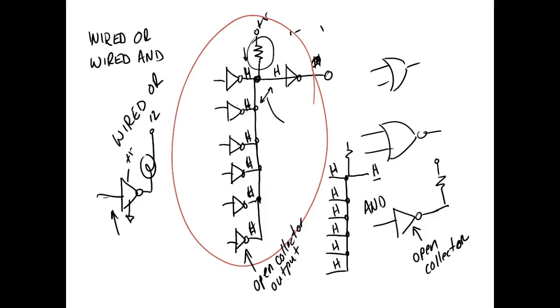Eventually, you can load it and you can short out the output of a standard TTL gate. But you don't need to do it very long, right? You understand? Because it's going to try to be sourcing 600. This other guy was 100 milliamps through that little 130 ohm resistor, and if you do it very long, you're going to mess it up. But it's good enough to troubleshoot. So yeah, we can jump out. We can ground the output of a logic gate without hurting it, so we can see what effect it has down the line. In fact, we got a thing called a logic probe that basically that's what it does. A pulsar probe.